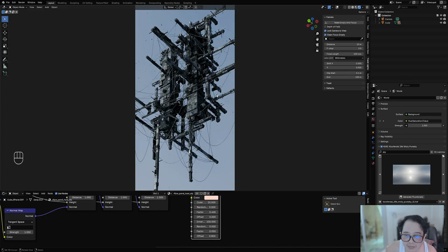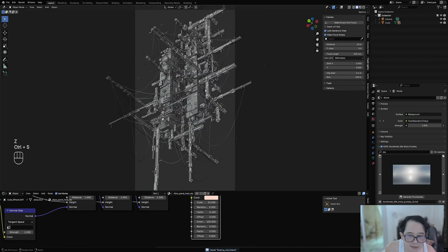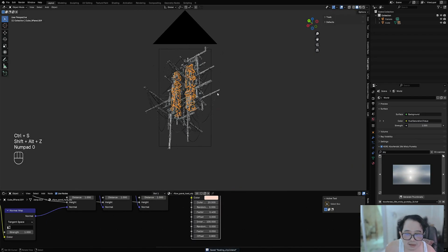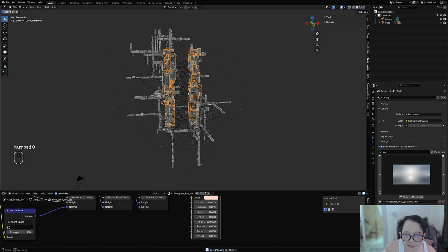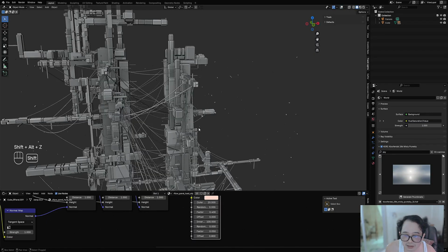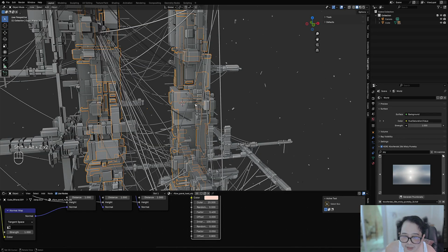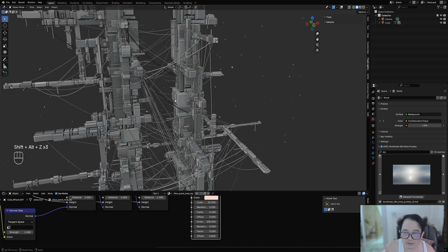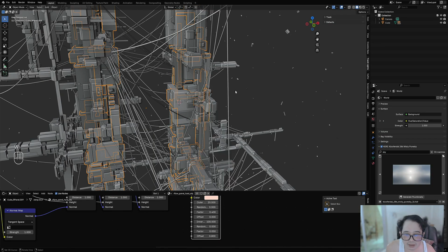Okay, you can probably introduce another light at the back here. Let's click the 3D cursor there. In order to stick the 3D cursor on the surface of the mesh, you can press Shift Space in the viewport and select 3D cursor.